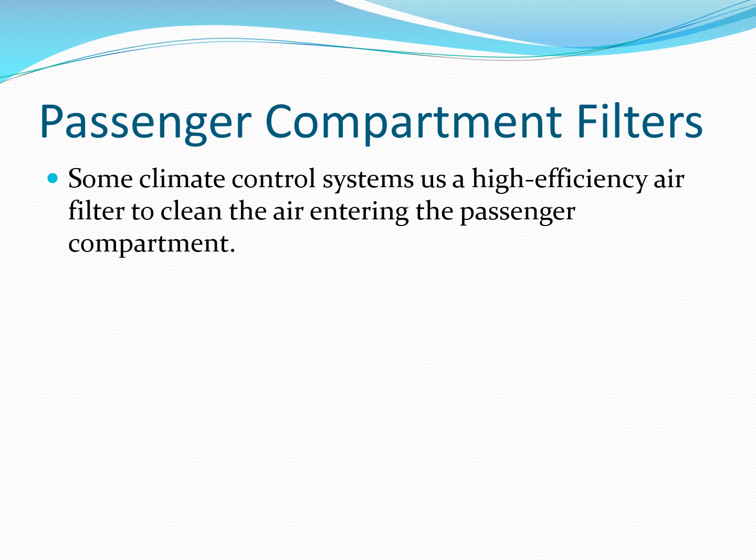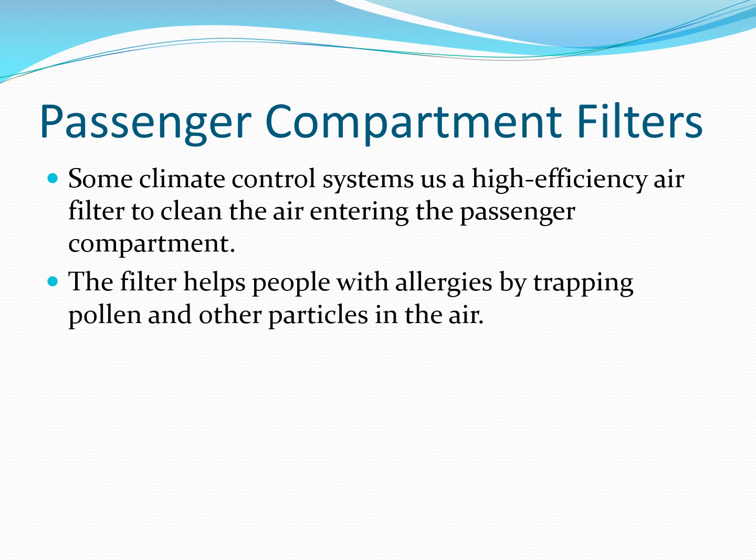This is something fairly new within the last decade, that we now have these passenger compartment filters that can become clogged. These are a high efficiency filter. This helps prevent allergies by trapping pollen and other particles in the air. However, what this can also do is, if the passenger compartment filter is never changed, then this could create a blockage, an air blockage.